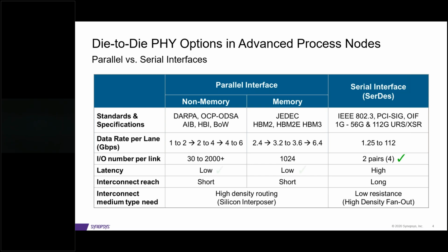So overall, at the very high level, there are some advantages in the number of links and latencies. Again, very general. And of course, it depends on your design type and how long your connections are from die to die. By putting a die right facing another die, it's easy to make short connections. But when you have many devices in your package and you have to make a lot of routes that are not just directly within a few millimeters of each other, then you're talking about longer traces that are needed. And that's where SerDes becomes more attractive.